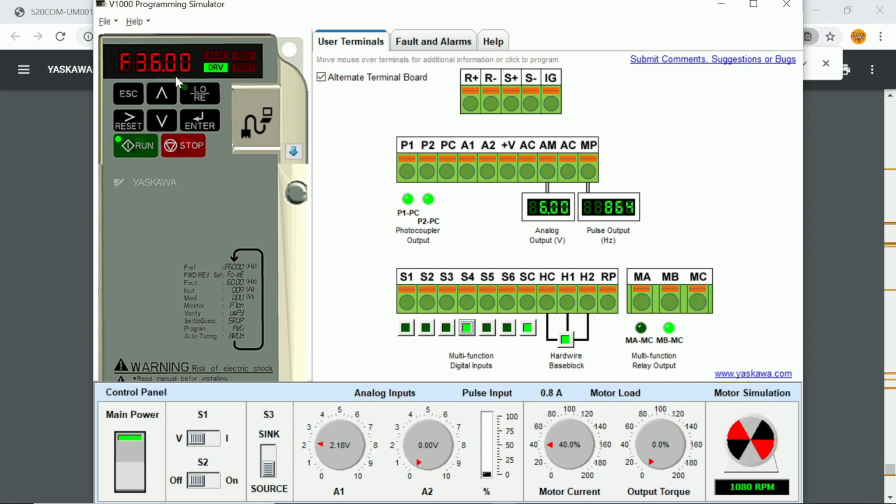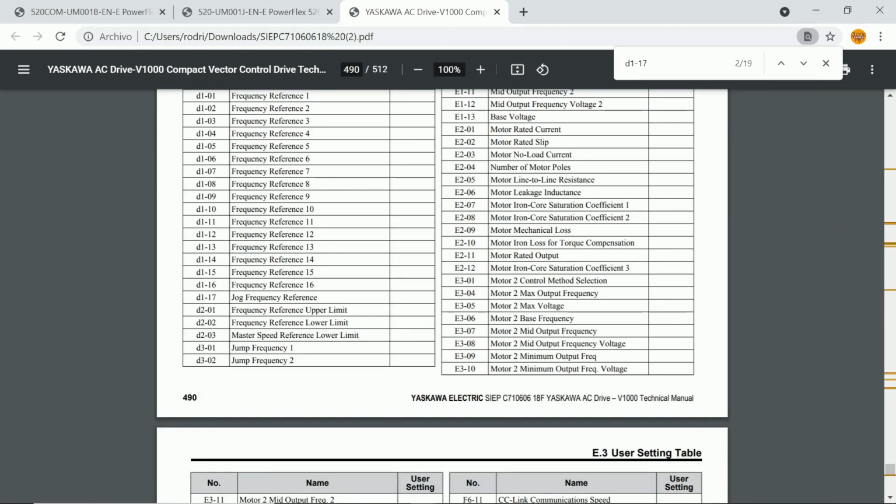So that's what we do when we jog this. Now, what did I do? The input that I wanted to assign, we assigned our parameter. We assigned whatever value to our parameter. In this case, it was 12 to H1-04. So that input was for this specific function.